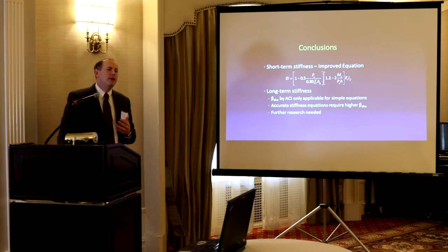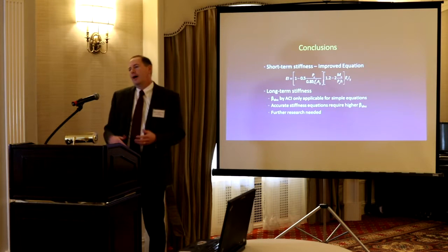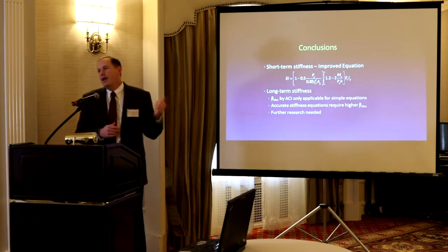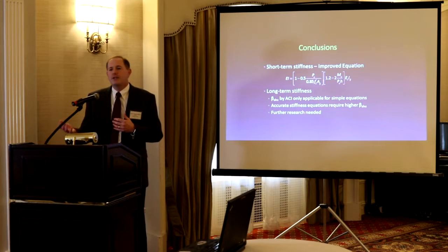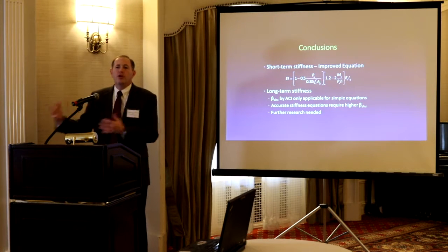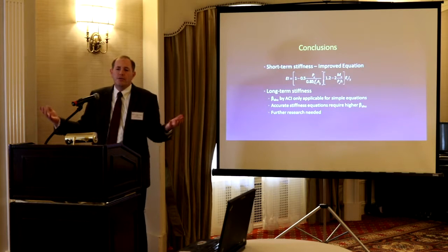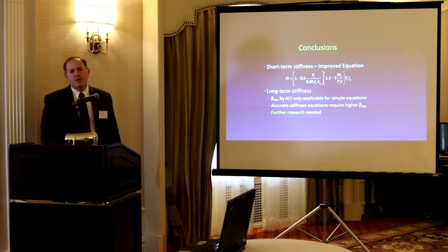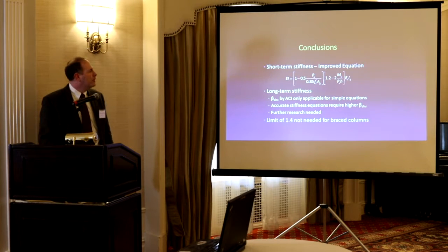Because again, it's one thing to say, say we're talking about crack control, but if I'm a little off on the cracks, fine. I don't want to have a column out here where we're significantly underestimating the moments, that we're going to put in the code that can be used for every building that we're going to design with. So I feel very comfortable in the short-term stiffness. We could codify that tomorrow. It's just the sustained effect we have to bring in.